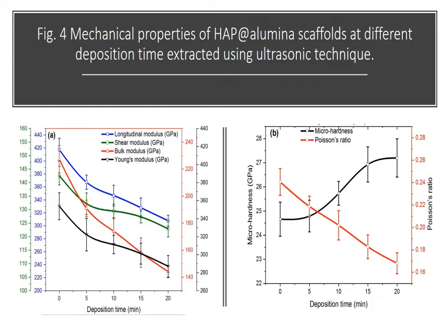The reduction of the elasticity and the elastic modulus introduced a beneficial way to keep the implanted biomaterial, because it drops the stress shielding, which occurs when the implanted material holds an elastic modulus higher than the bone itself, because this may lead to weakening of the bone.